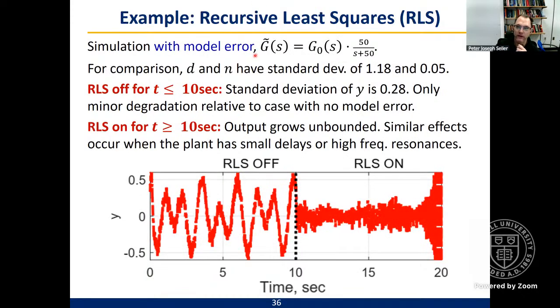Now, if you add just a little bit of model error, so this is the design model, that kind of simple fourth order model that I had a few slides ago. But I'm going to simulate the plant by just adding a low pass filter at a very high frequency. And I'm going to run the same simulation.